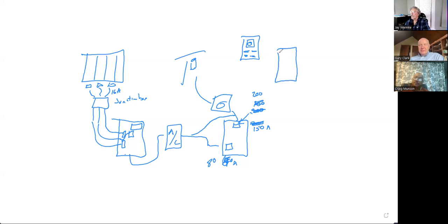Yeah. So if I've got a service panel here, and let's say this is my main, and that's going out to the meter, then typically you've got bus bars going like this. And then oftentimes there's a connection point down here at the bottom of the bus bar. You could run wires to another service panel and connect in at the top of the bus bar here, and then have additional connections. So all of that is possible. Or you can also put a big breaker down here and run to this other service panel, or have another breaker down here like a main.